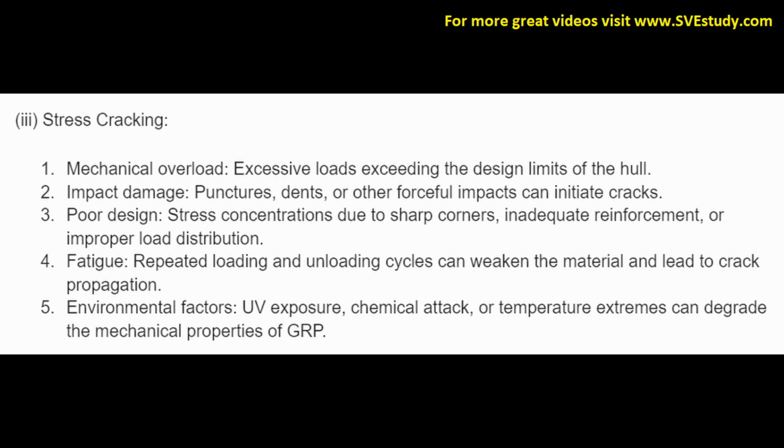4. Fatigue. Repeated loading and unloading cycles can weaken the material and lead to crack propagation. 5. Environmental factors. UV exposure, chemical attack or temperature extremes can degrade the mechanical properties of GRP.